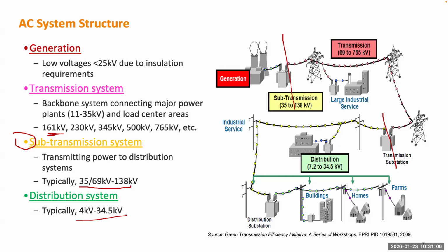If you still remember how we calculate power flows, the power system has different types of buses. You have a generator bus, which is called a PV bus. We have a specified power P and voltage magnitude. We need to solve the angle and the reactive power. And for load buses, we can give the P and Q, the active and reactive power, but we need to solve voltage magnitude and angle. So each bus is actually representing one distribution system. It's just a simplified distribution system.